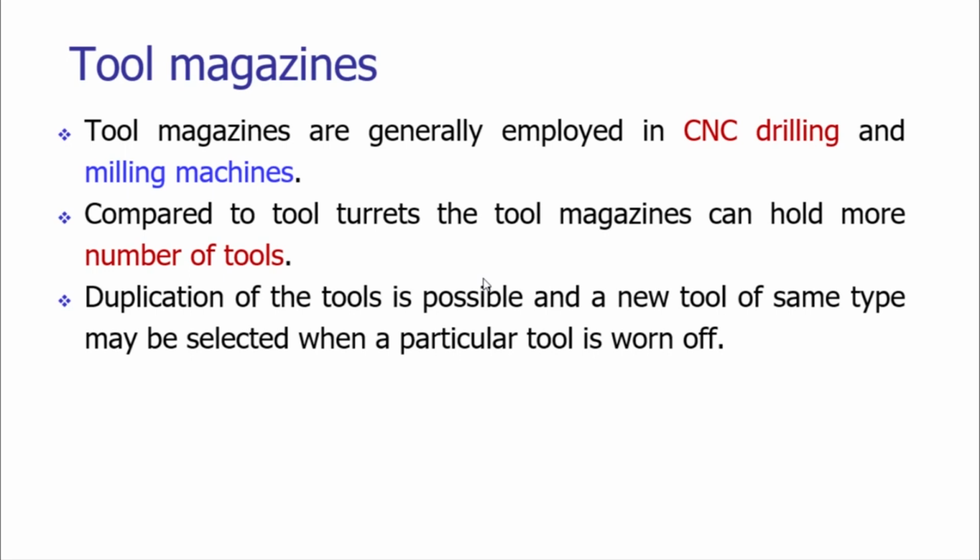In general, in a tool turret, we can accommodate around 15 to 20 tools easily. But when we are trying to have a variety of operations carried out on the work part, say drilling operations, pocket milling operations, slot milling, finishing, and so forth, for such operations we need an arrangement which can store many tools.